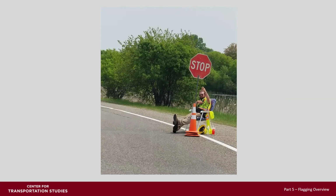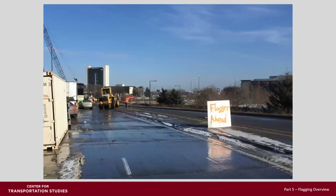Sometimes it's boring on lower volume roadways and it's hard to stand there all day. That's understood, but you should be standing, facing traffic, and properly attired. Use of hand-painted signs is not allowed. There are standards for the signs. Retroreflective signs must be used in all work zones.